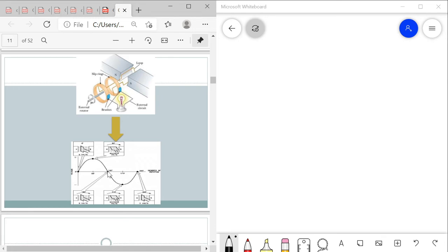It increases again until the conductor is parallel with respect to the lines of force, so it generates the negative maximum voltage or current. The complete cycle ends at a perpendicular position again, at 360 degrees, or zero EMF. So you can generate maximum voltage or current when the lines of force are parallel with respect to the conductor.